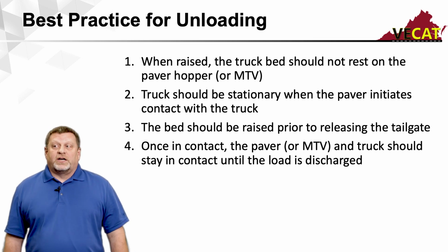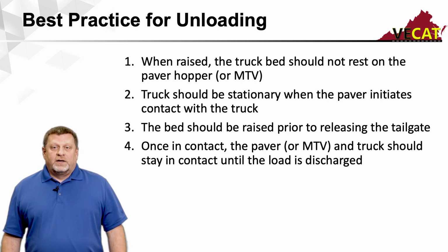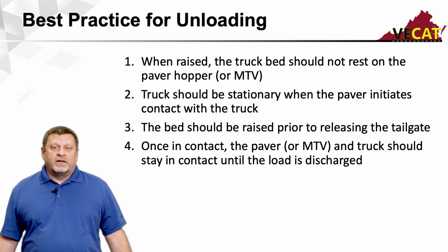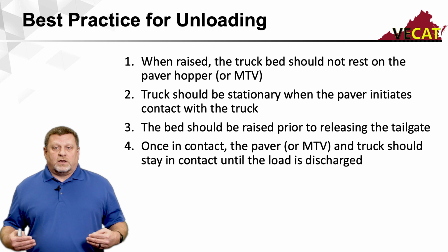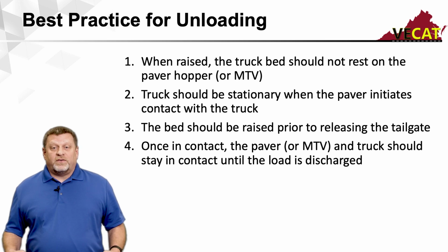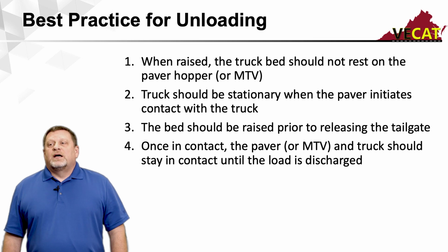The truck should be stationary. What we want is for your truck to stop in front of the paver, then put it in neutral and allow the paver to make the contact with the truck. If the truck backs all the way up to the paver, again, it's going to affect how that paver is moving and placing the mix, and it'll be seen in the final roadway. So we want the truck to come to a complete stop just in front of the paver and allow the paver to initiate that contact.